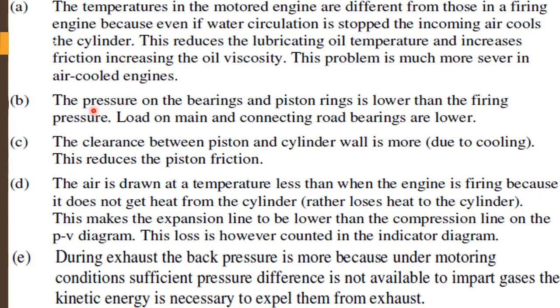Second, the pressure on the bearings and the piston ring is lower than the firing pressure. The load on the main and connecting rod bearings is also reduced, because there is no firing and no excess temperature rise. The clearance between the piston and cylinder wall is more because of the cooling.